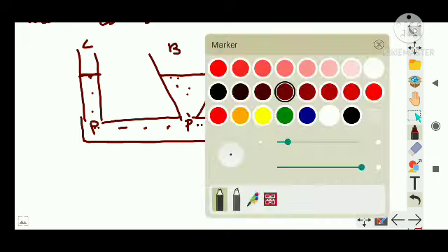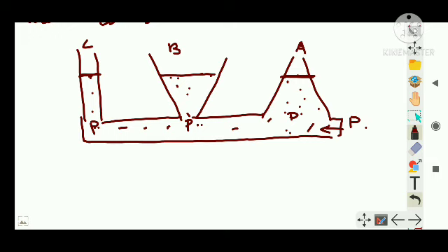See, suppose I have a container like this, I am pushing water, so here the pressure will be higher and here obviously is a constant pressure which is lower. So it will keep rising again and again. Here also, I apply a pressure P itself. At that point, no more rising is allowed. So when the upper pressure and lower pressure are equal, only then does the water rising stop.